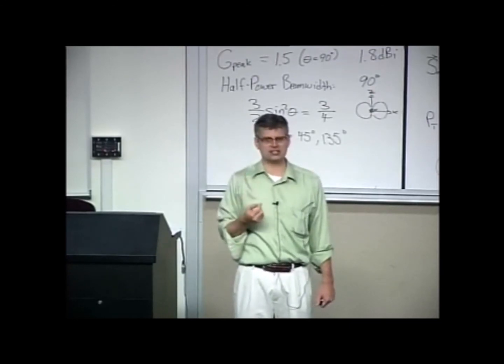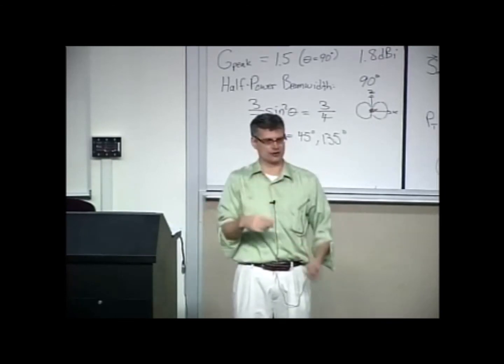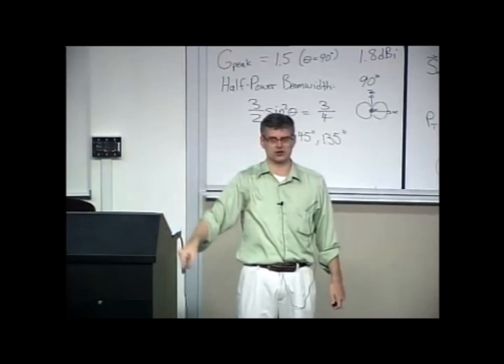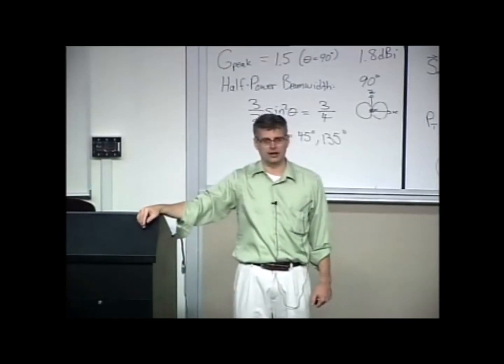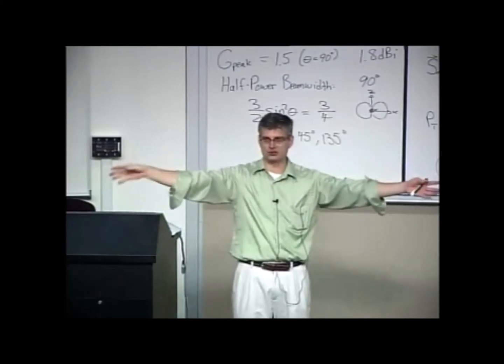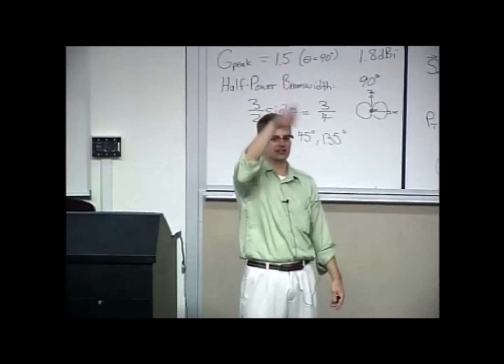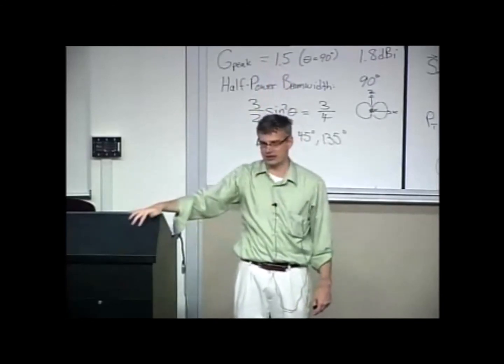Or you say, oh, yeah, that's a good cellular antenna. It's clearly sectorized here and has a lot of gain along the horizon where all the paying customers are. Oh, that's a good radar antenna. It's very wide in this direction and narrow in this direction. I know that's going to send a pencil-thin beam that captures all of the elevation angles I need to track aircraft.